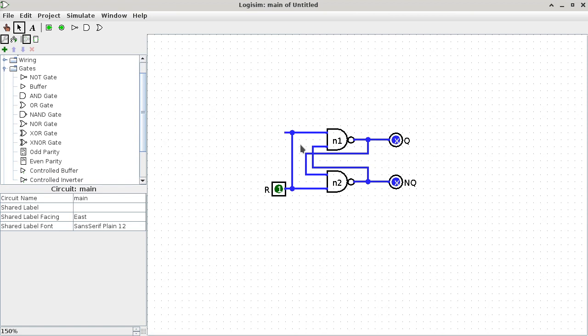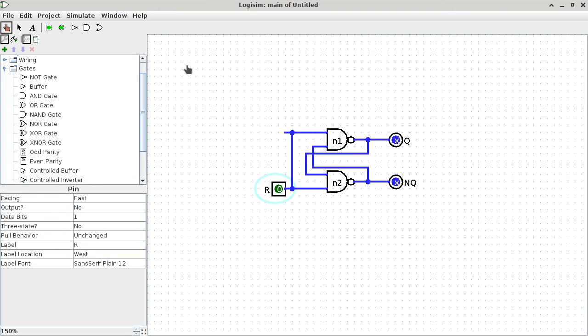Okay, so with this, I can now reset one pin to 0 because that was the initial state, and then I re-enable simulation. And the moment I click this, it's going to start the oscillation. Okay, so we got 5, 4, 3, 2, 1. And Logisim is smart enough to detect that oscillation apparent, which basically means we do not have a steady state.